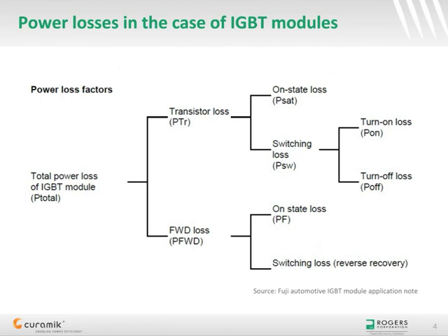As already mentioned before, semiconductor devices generate heat during operation. Let's look first at IGBT power modules. Transistors are not ideal switches, and a portion of the input electrical power is lost. In the on state or conductive mode, the voltage drop between collector and emitter is not zero, and once multiplied by the collector current, we end up with significant conduction losses.